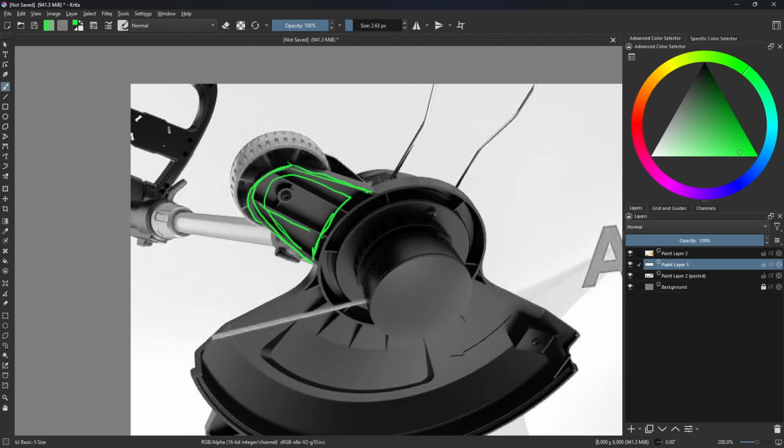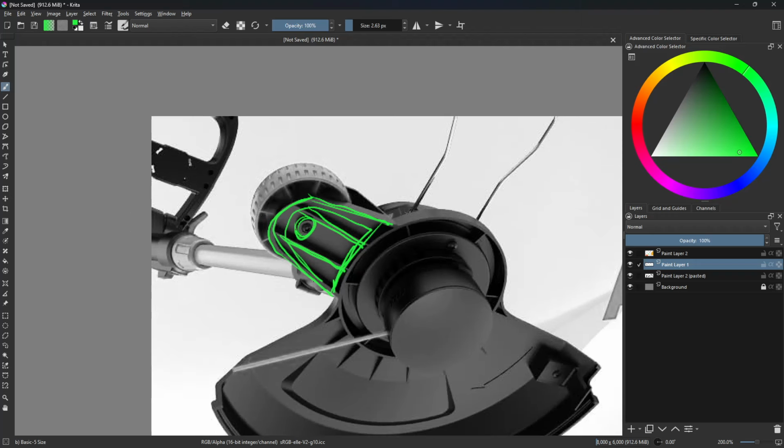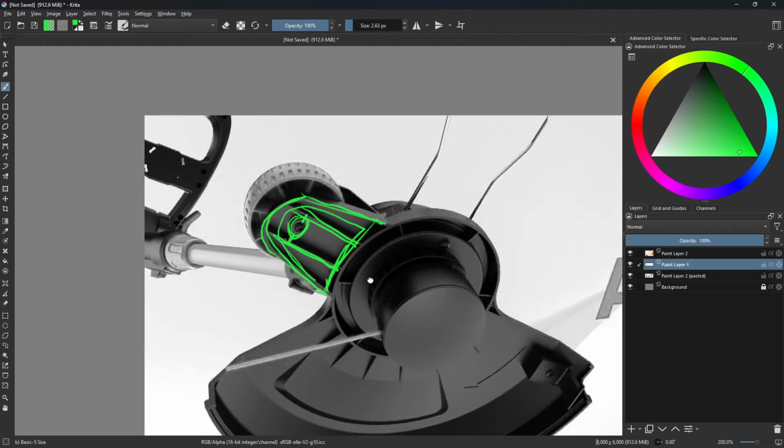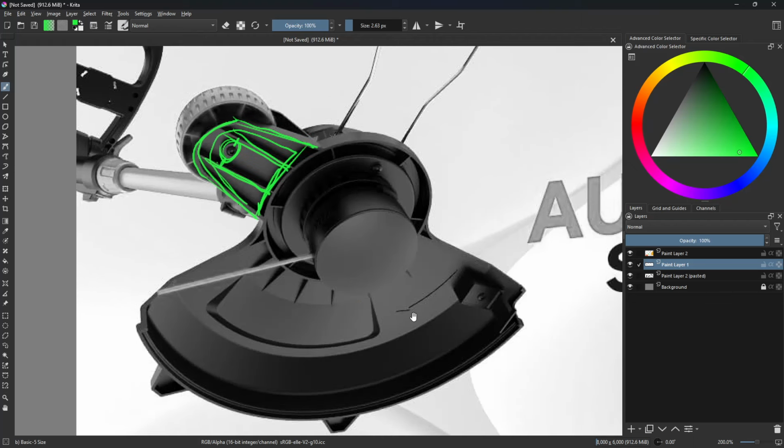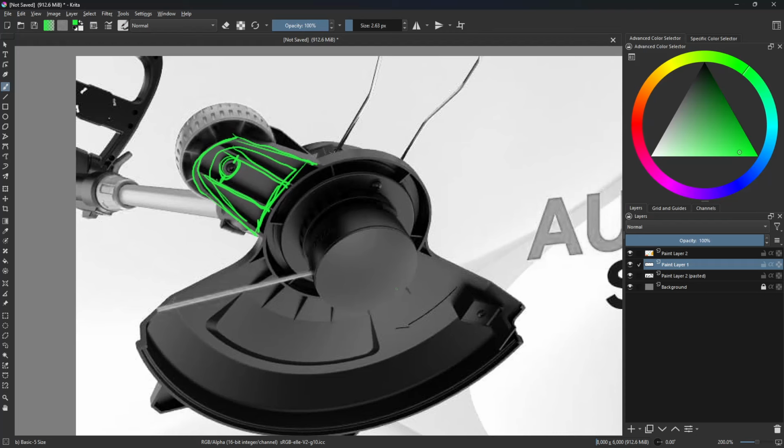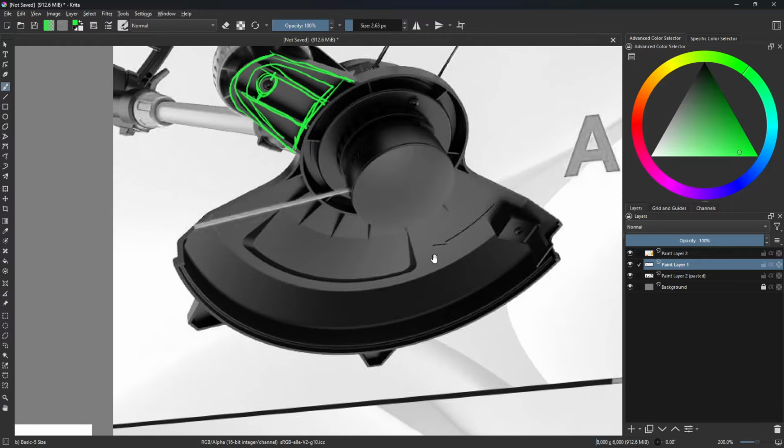Then you do a Boolean union that adds that plastic piece back, right? So it's really like 3 shapes you're making, and there's a cylinder in here, so it's about 4 or 5 shapes for that. You Boolean it all together on more of a blockout, simplified mesh. It'll be pretty close to what you want. And then you could convert it into subdivision if you wanted to. So there's always tricks like that.